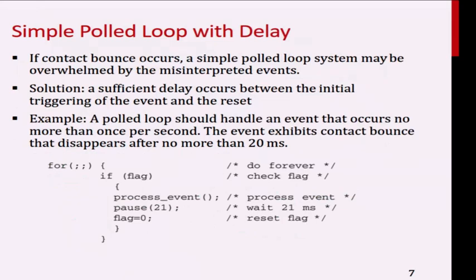There is also the option of having a delay. Why do you want a delay? Basically to handle the cases of what we saw earlier, which is your contact bounce. So if, for example, I am connecting it to a switch, then I know that when my switch is pressed, I may want to capture the event, but it will also trigger multiple events like this before it settles down. You must imagine that your processor is always running much faster than all these mechanical transitions.